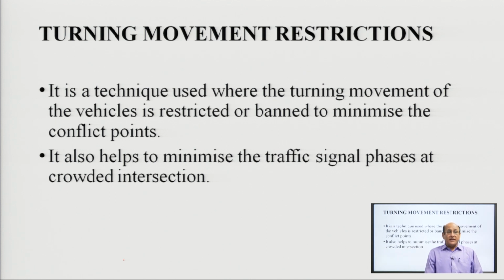Turning movement restriction. It is a technique used when the turning movement of the vehicle is restricted or banned to minimize the conflict points. It also helps to minimize the traffic signal phases at crowded intersections.